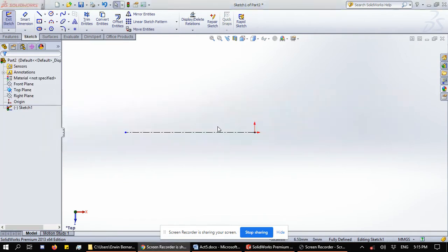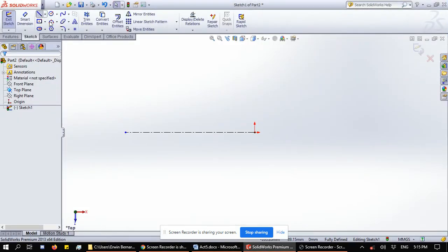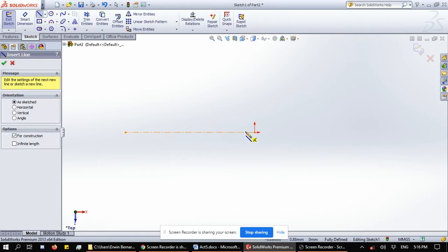As you can see, this figure consists of multiple center lines. When I practiced it, there are problems that I encountered in which the sketch will be overdefined. So with optimizing and simplifying it, we'll be using only three center lines here, and we will be moving this point here to the center. To show it to you, we'll be creating three center lines, which can be anywhere first.